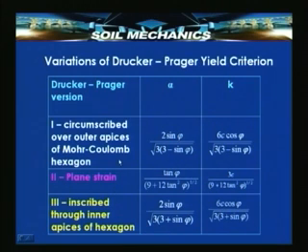Suppose the soil is subjected to 3-dimensional stress state, alpha will be given by 2 sin phi by root of 3 into 3 minus sin phi and k by another similar equation. If plane strain conditions prevail, then tan phi by 9 plus 12 tan square phi to the power of half is the corresponding applicable value of alpha.